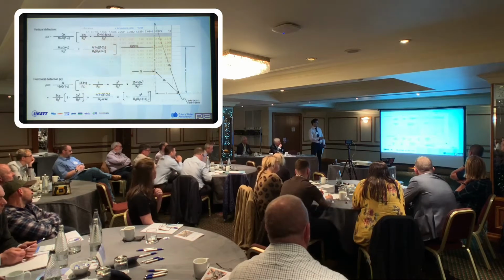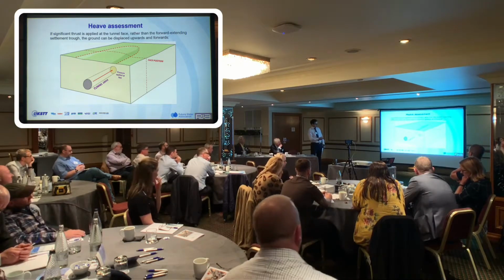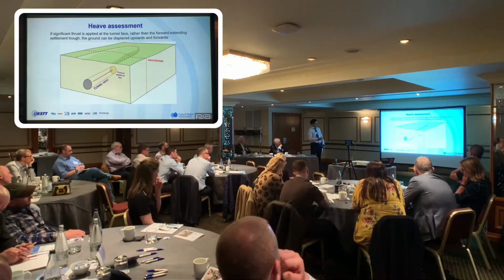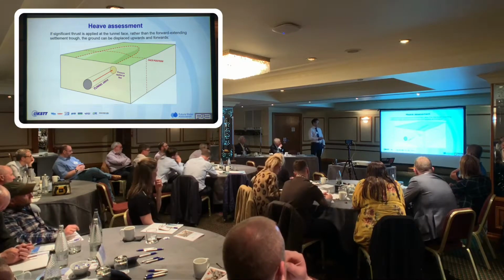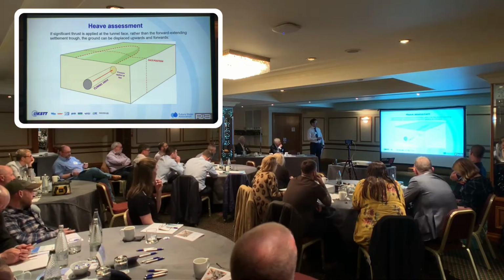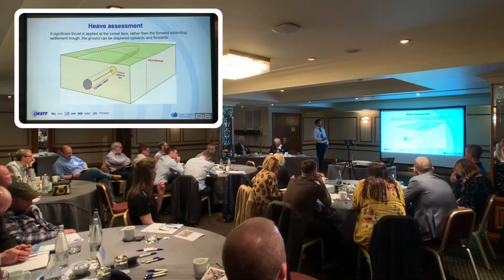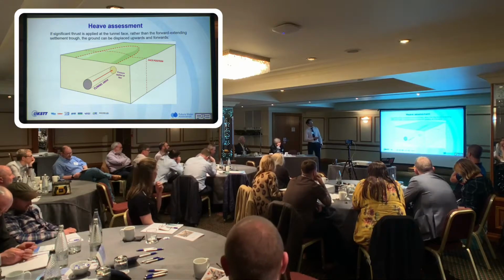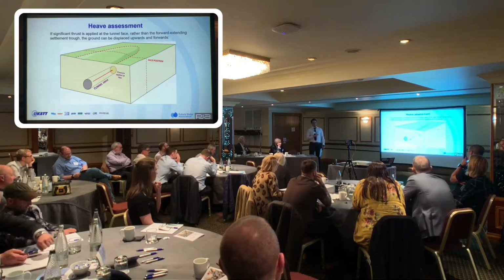So if you go back to here, you've got a situation where you've got a bit of settlement occurring behind the tunnel drive as well. As it often will, it heaves, and then as you've gone past that section, the heave will drop. So it's almost like a wave passing through along the line of the drive itself. But again, all these things have to be considered, and limits have to be defined, especially in situations where you have services and structures.